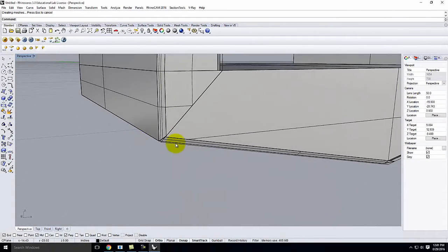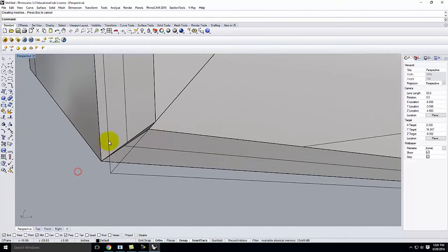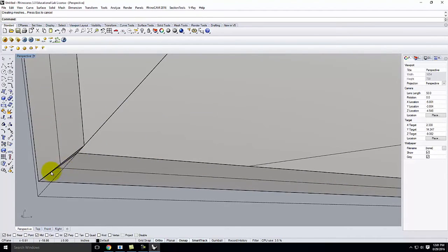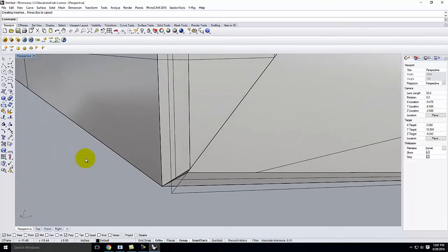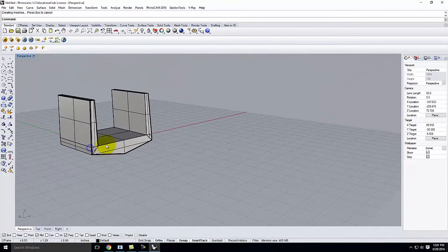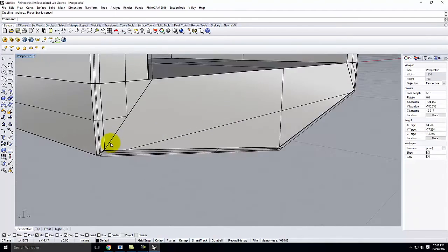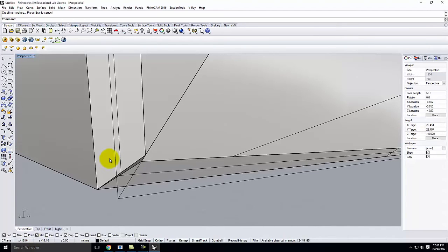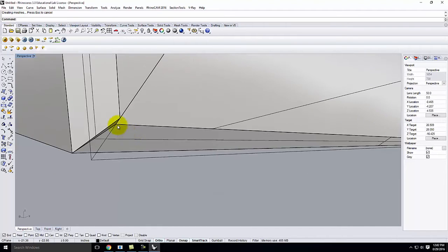However, when we start to look at these bottom corners, if we look at them closely, you can see that we have some issues. And so one of the things that's important to recognize in the world of V-Ray is that if we were rendering this as a bridge with a bunch of pieces together, the fact that that corner isn't perfect doesn't really matter, because it's all going to go away when we render it. However, if we were going to 3D print it for some reason, or we needed to use the CAD/CAM router to cut out pieces or something along those lines, this would present a big problem because this shape is what's called not watertight, which means it couldn't hold water if it was full because it has this crack here.